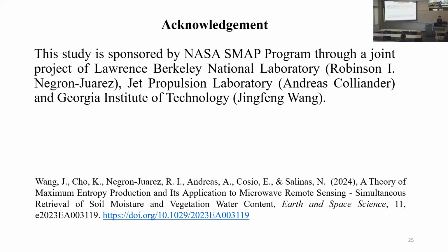They downscale to 9 by 9, but they have to use supplementary data based on vegetation cover, which usually has a higher resolution. They can separate them to get the finer result, but that's processed data, not the original signal. The original signal is still 40 kilometers. You can split it into 9 kilometers in post-processing, but the information at 9 kilometer resolution is actually not there. It's the same problem we have with SMAP when there's snow of different depth.